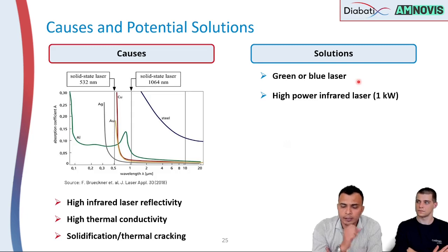Thing number one is that the quality of those lasers is not yet there compared to infrared lasers, which is typically measured by the so-called M² factor. And second, the cost of these lasers is still high. These are two challenges still to be tackled for visible lasers.